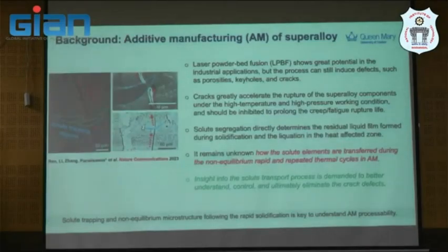So now, what happened to the cracked sample? The cracked sample, actually, we identified this crack propagation that we said is due to the ductility dip here. And you will see that there is a zone that trapped it, and probably they changed the microstructure a little bit from columnar to kind of equiaxed. And then this is a dark shade zone. And then we try to make a hypothesis of what happened here, why it actually stopped here, rather than penetrate through this crack. And this is another